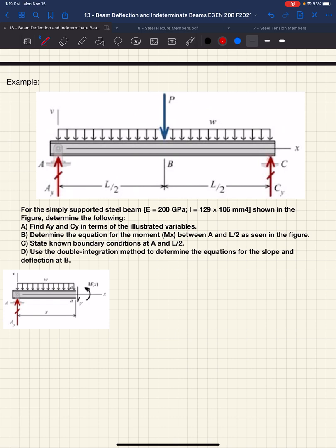Right, an overall free body diagram. Essentially half of it's done. And then as part of that, we needed to come up with the deflected shape. What do we think the deflected shape of this would look like? Maybe something like this? A U. A U. So based on this, the steps are to create a global free body diagram, assume a deflected shape, and then determine our reactions. We have to determine all of our external forces so that then we can cut it again, which is the next step, so we can get an internal force.